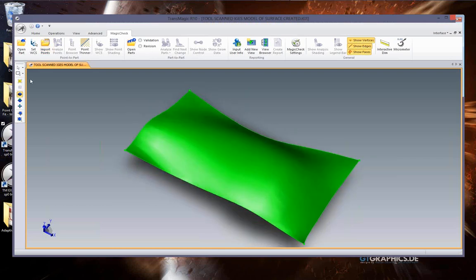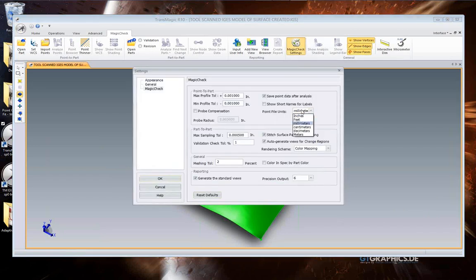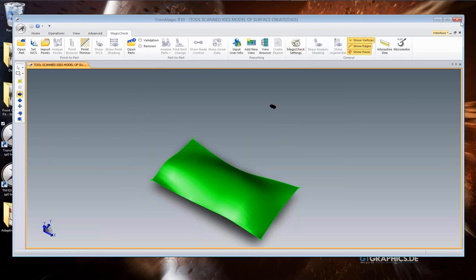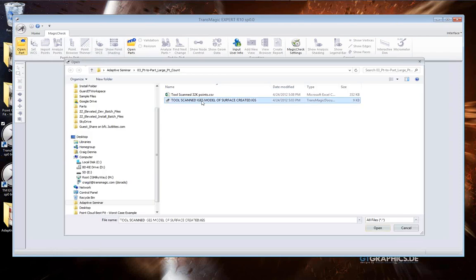There we go. So exactly what I expected. This was a millimeter point set. So you'll notice this. This is good to see what happens if you didn't key in the values correctly. My scale was actually at inches, so I should have had this changed to inches. Again, this is just up to the user to know at what scale they measured those. So essentially, you just have to change your value and re-import.